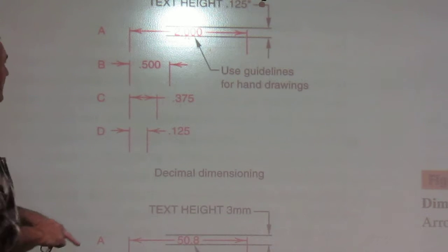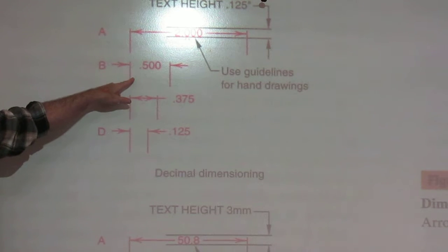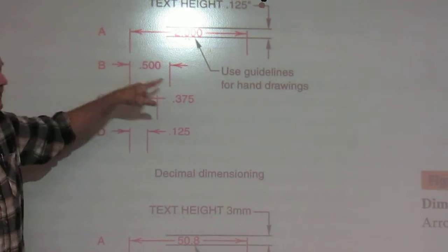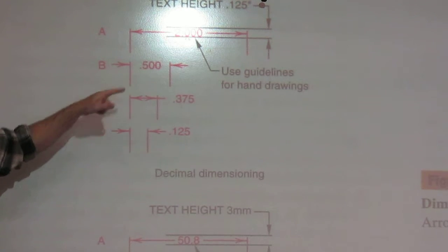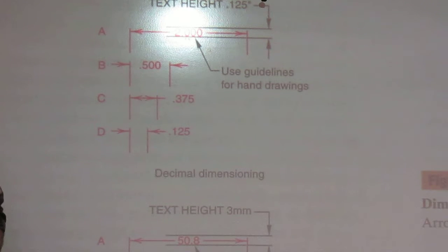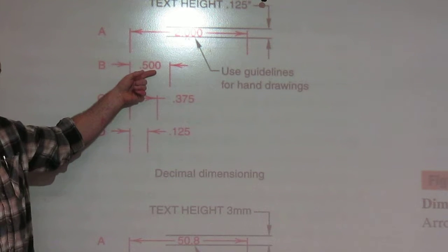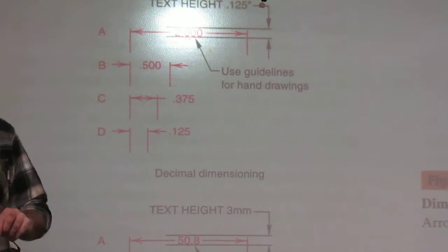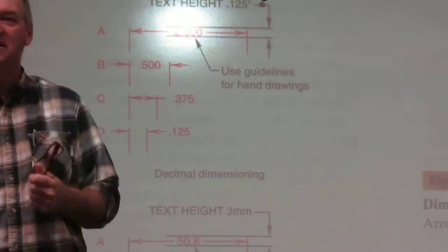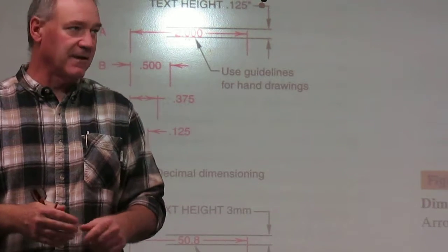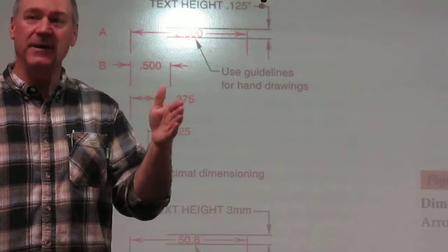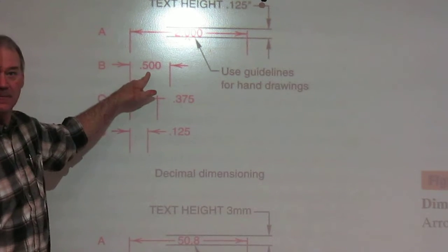Now, as things get smaller, though, you aren't going to be able to do that. So when we come smaller, the first thing we always do is pull out the arrows and the dimension line. We pull those out, leave the text centered in. Now, keep in mind that we're at 2 decimal places for the most part. If metric, we're at 0 decimal places. So you've got to have at a minimum 3 places in here, right? 1.00 or 0.085, whatever the case, 0.8. So you're going to have 3. That's going to require about 1/4 to 3/8 to get this in here.